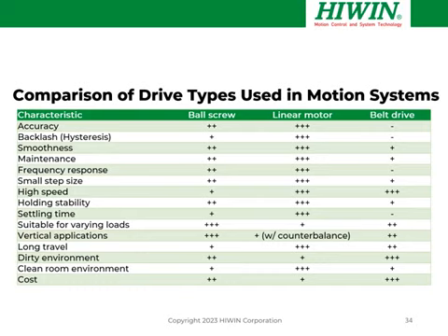Ball screw is ideal in a vertical application. We can apply a brake to the motor very easily to support that payload. A linear motor, you're going to need a counterbalance. One nice thing about a linear motor, you can go very long travels. In fact, there's really no limit.